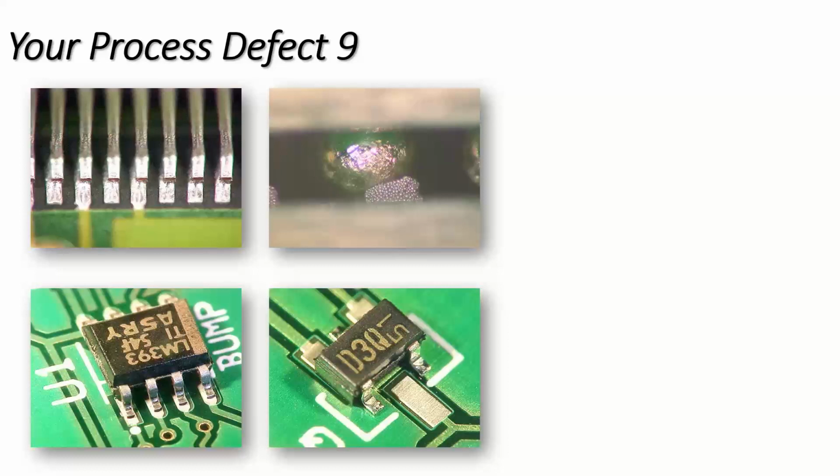With a lot of defects that we have today, where you can't actually see a product, the different techniques you can use obviously is X-ray. I can use X-ray to look at voids. I can look at X-ray to look at dendrite formation, corrosion underneath packages. So X-ray is a great tool.